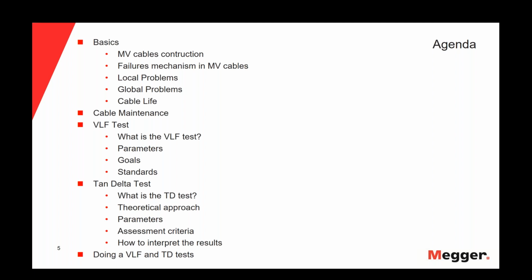We'll continue talking about the Tan Delta test. What is the Tan Delta test? We will use a theoretical approach to show how the Tan Delta test works. We'll continue talking of the parameters, the assessment criteria, and how to interpret the results. And we'll finish this webinar doing a simulation of a VLF test and a Tan Delta test using the VLF Sinus 45 kV of Megger.